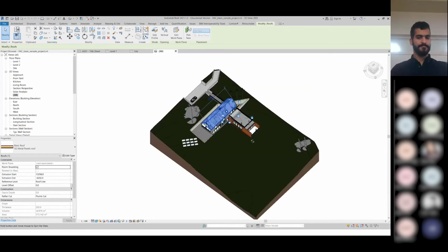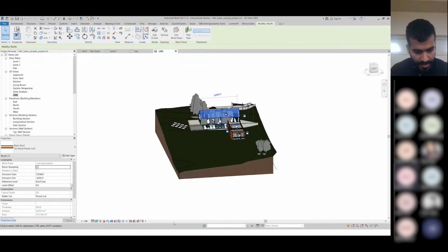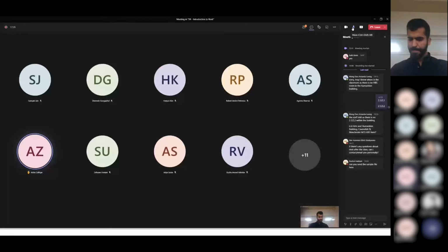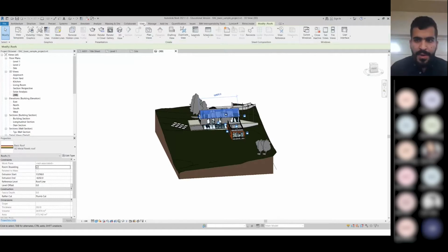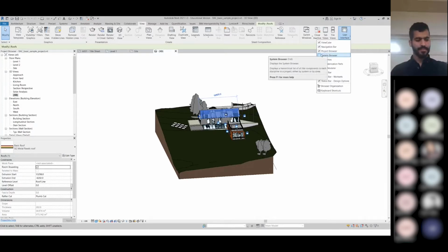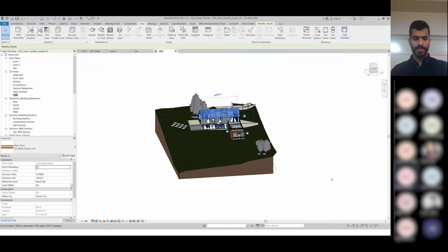Mahmoud, sorry to interrupt you. What if you can't see the project browser? Okay, if you can't see the project browser, go to View, User Interface, and it should be there: project browser. Thank you.